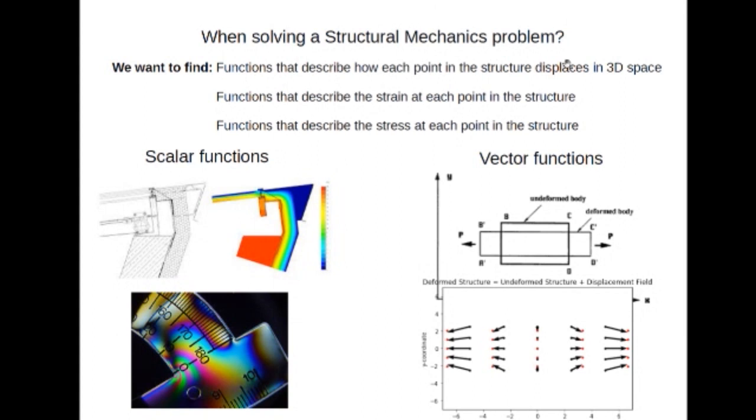From the displacement field, we can relate to strains, and we'll do a derivation of three-dimensional strains so we get comfortable with where that comes from. But again, I want to make sure that you understand the difference between a displacement and a strain. A displacement is how a point moves, irrespective of its neighbor. It doesn't care what its neighbor is, it's just how that point moved specifically. Strain is the relative movement between two points that are close to each other on the structure. And that is something that's related to the stress.